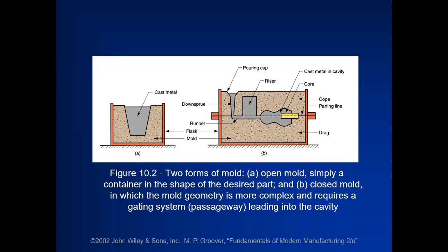The open riser gives us information about filling of the whole cavities inside. So the purpose of the riser is to provide the molten metal during the shrinkage process. During the solidification process, it compensates. Okay, so a few things I will explain in this.